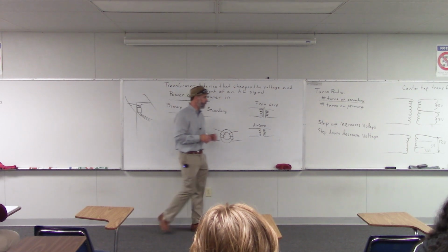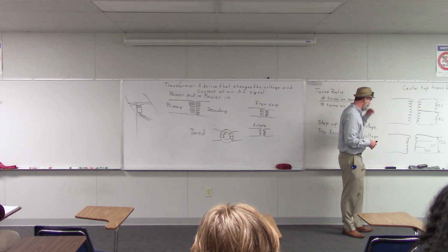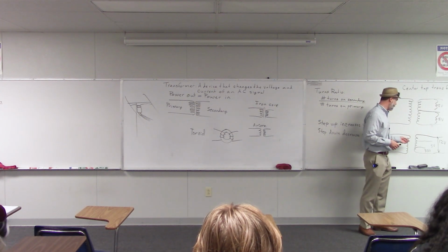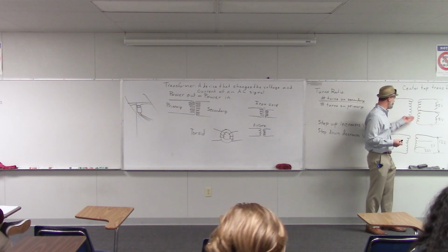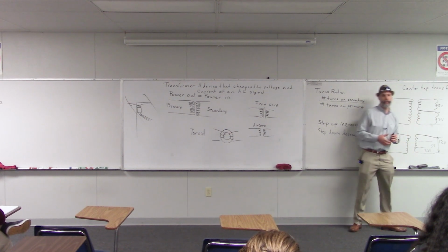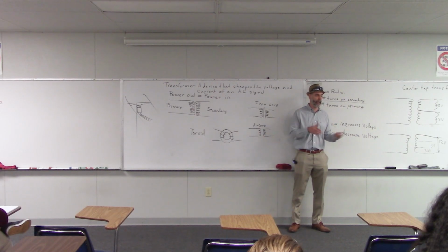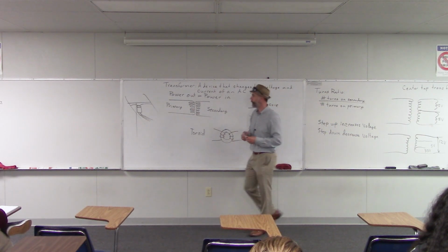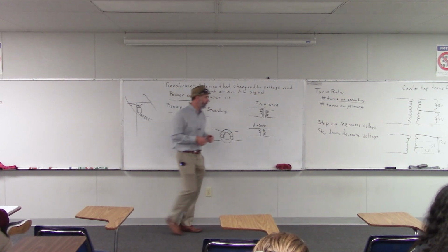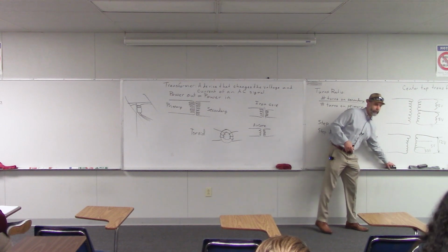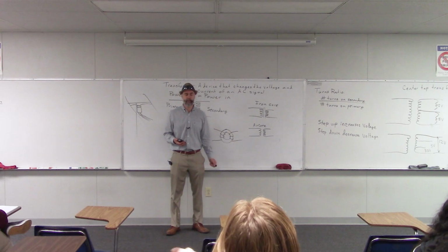All right. And then the other term I wanted to mention was an open winding. An open circuit is just a circuit with a break in it. An open winding is the same thing. It's a winding that has a break in it. So if we say that there's an open winding, it just means that there's a break in one of the windings. Okay? Questions about that? Is the center tap always on the secondary that's tapped like that? Yes.